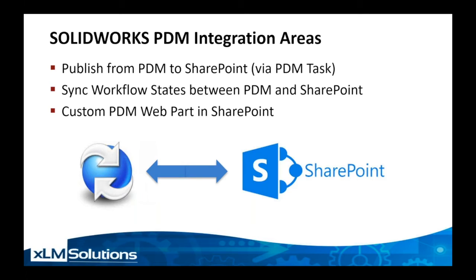Another area where we see integration points is syncing workflow states between PDM and SharePoint. So obviously in SolidWorks PDM, you have your workflow with various states. In SharePoint, you can put statuses on the data, and by doing a change state in SolidWorks PDM, it can change the status in SharePoint, or vice versa.